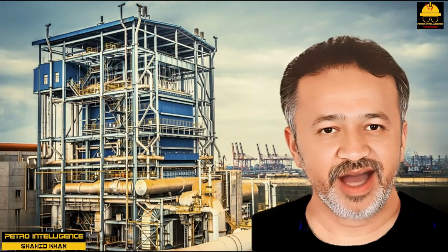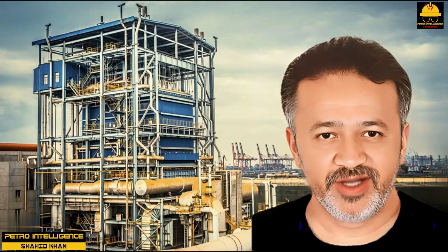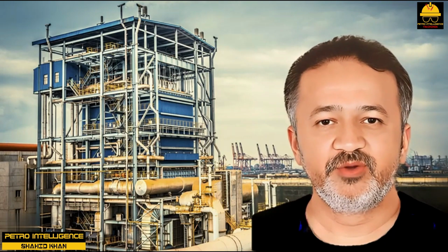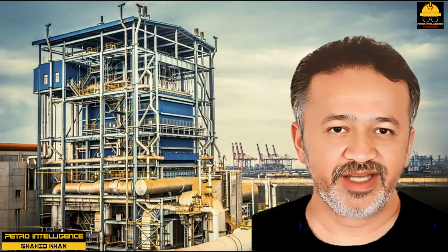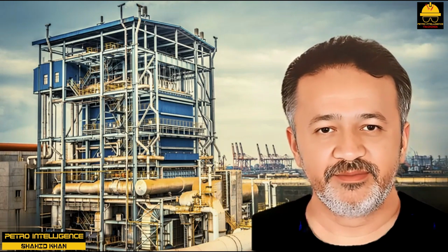The objective of the design was to produce an exchanger suitable for heating or cooling of slurries and other process streams containing solids and/or fibers. Spiral heat exchangers are constructed by winding two long strips of plate metal around a center to form a spiral body, which then contains two concentric channels.